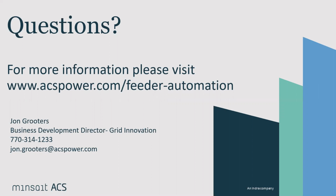If all your communications terminate at the control center, so all of the field devices you'd be communicating with communicate back to the control center, then the hosts, which can be redundant with automatic failover, can be deployed at the control center. If you only have communications available in a portion of the network, say from a substation outward, or a set of substations in a particular area, then you can deploy the hardware out in the field at those locations. So it's flexible in that sense.